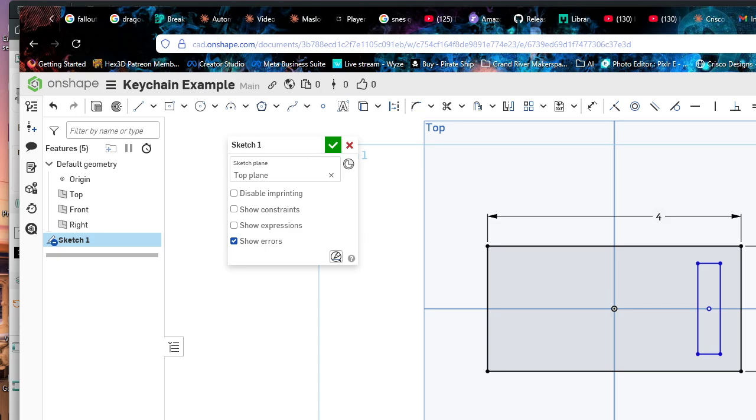Kind of like the film reel sketch you had earlier. For that, I probably would have done a circle, and then I would have probably done the hub cutouts. I'll break it down into steps. It makes it a more robust model. It was one sketch, is what I'm saying. I would probably break it down to have different sketches for different features, because then if one sketch breaks, the rest of it doesn't necessarily break.